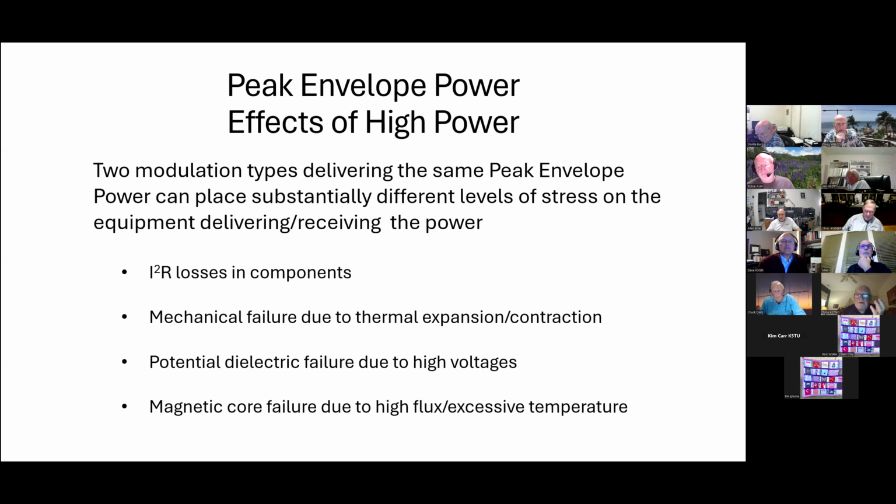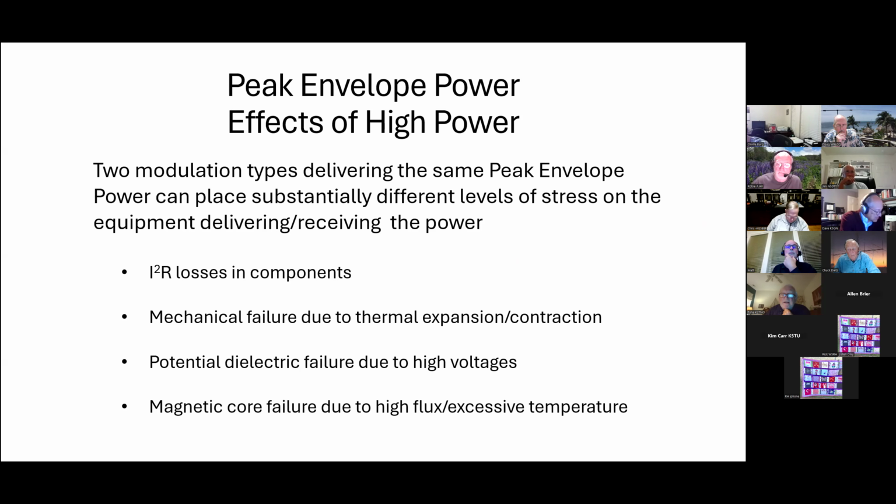Well, the reason I asked, I've got a friend here, KR4LO, who does a lot of RTTY, and he was in a RTTY contest last fall, and he smoked this 49-to-1 balun that was in his end-fed half-wave antenna. In our looking around, he built another one with more toroids used in the winding. But from our reading, I thought that once that core has been heated above the Curie temperature, I thought that was permanent. Could you comment on that, please? So you are correct with Curie temperature.